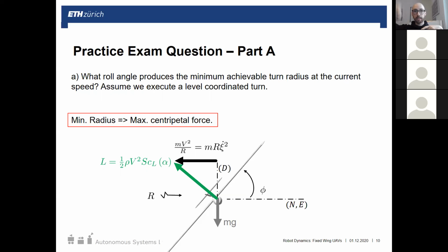But when we're talking about the full plane, we sum everything and lump it at the CG, so the angle of attack is no longer from the wing's chord line. It's from the body axis of the plane. That's the difference between full aircraft and 2D airfoil analysis.